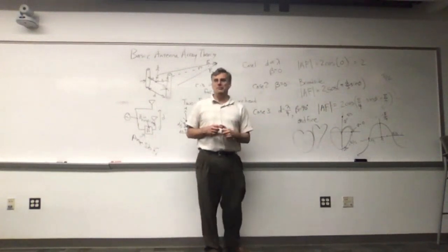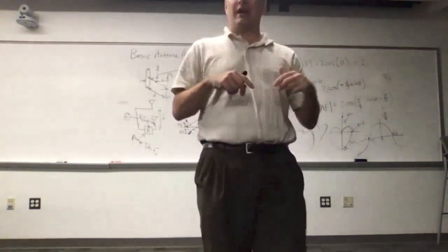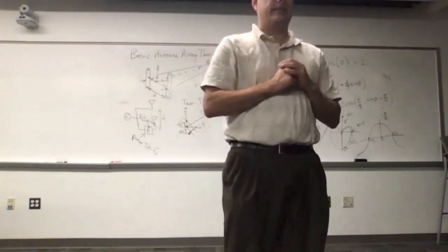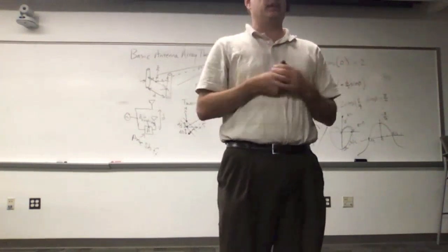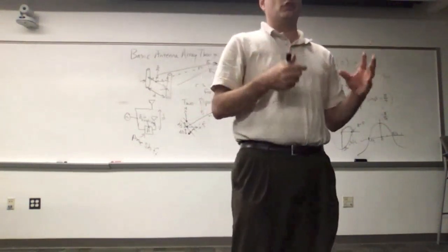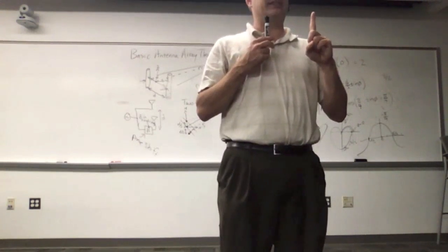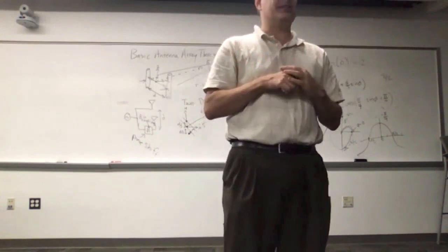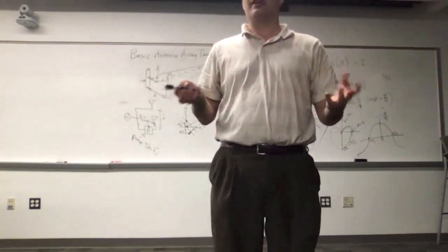Lambda over 2 is a little bit better. That's nice. The electromagnetic apertures don't really overlap, and you can approximate everything as non-coupling. Yeah. You said that was parasitic. Parasitic capacitance and inductance. It depends on the configuration. If it's two dipole antennas, it tends to be more capacitance than inductance. If it's two loops that are close together, it's more inductance. But you can be guaranteed there's a good bit of both at high frequencies.